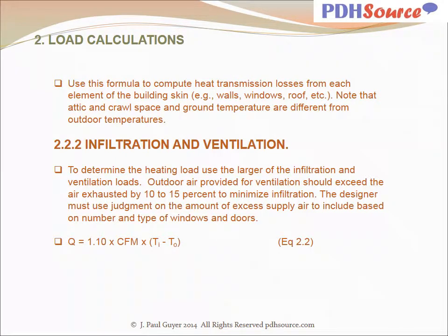This formula is used to compute the heat transmission losses from each element of the building's skin. Note that attic and crawl space and ground temperature are different from outdoor temperatures. In addition to the heating load due to transmission, there is heating load due to infiltration and ventilation.